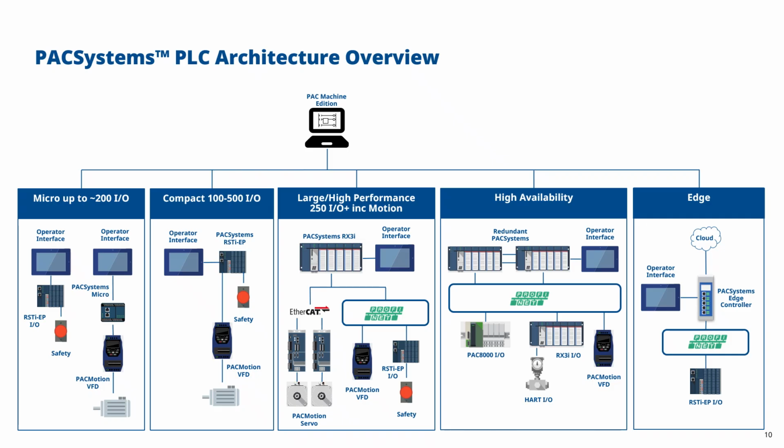I've seen some very small systems using an edge controller, but it can also do some very large systems, and the same with the high availability side. I would say that typically if it's a smaller high availability system, an edge controller redundant would make sense, but for larger applications, the PACSystems RSTi using reflective memory makes more sense. And then above this, of course, we have PACMachine Edition. PACMachine Edition is our programming software, and then you may also have the Movicon HMI SCADA. As I say, that's on a separate slide deck.